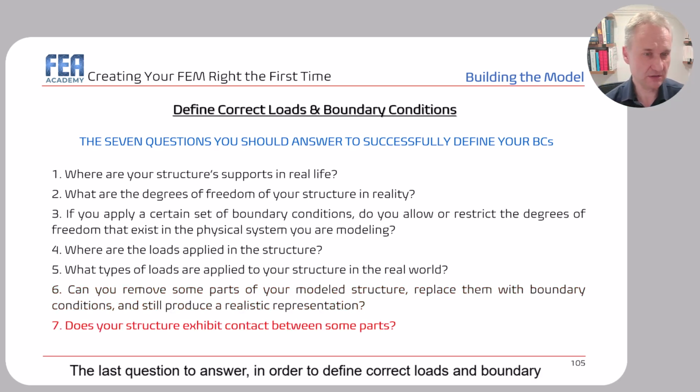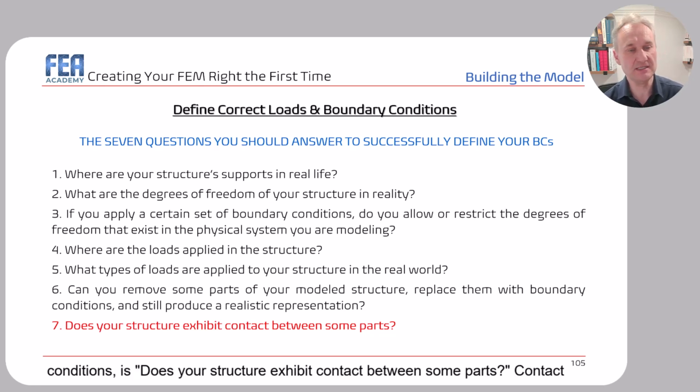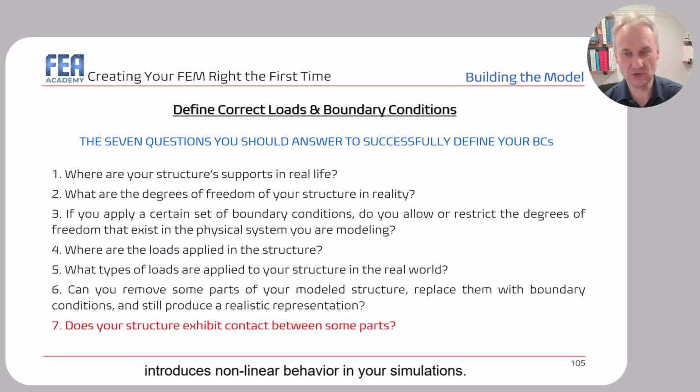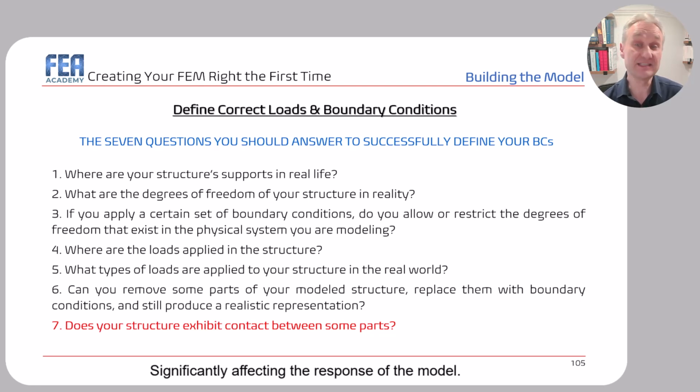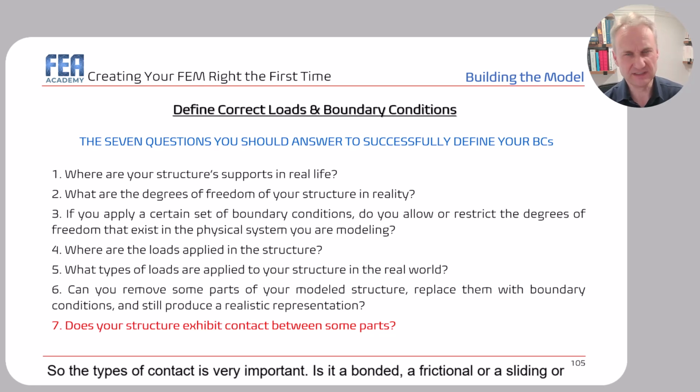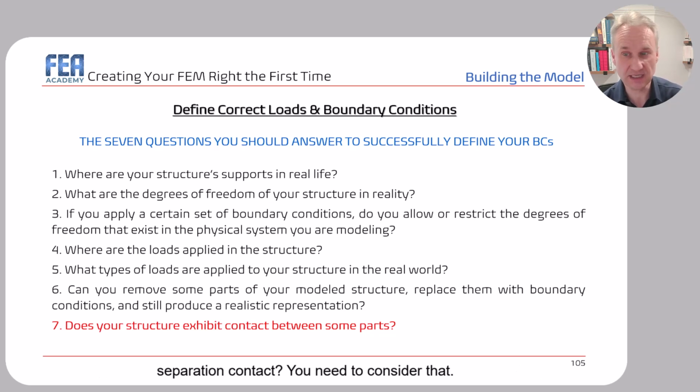The last question to answer in order to define correct loads and boundary conditions is: does your structure exhibit contact between some parts? Contact introduces nonlinear behavior in your simulations, significantly affecting the response of the model. So the types of contact is very important. Is it a bonded, a frictional, a sliding, or separation contact? You need to consider that.